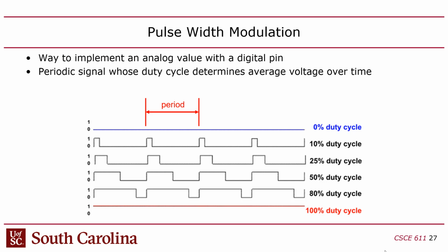But if you have a high-end stereo system at home that has a Class D amplifier, which are really nice because they're efficient, you lose some of the audio quality, but they're very power efficient. Anyway, a Class D amplifier for audio will have that low-pass filter that takes away the artifacts from the switching. But the point is, this is basically what you end up with as an analog signal.